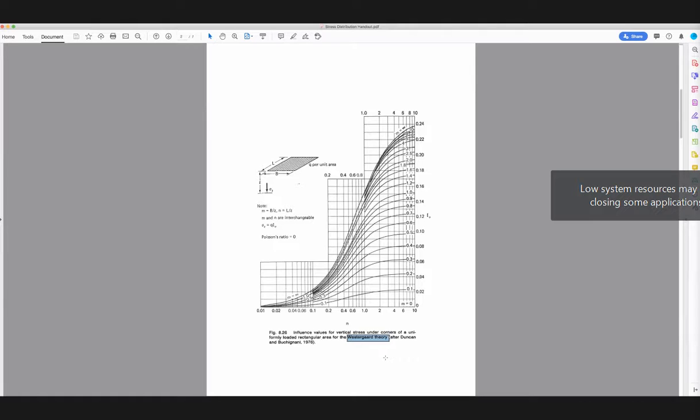But Westergaard added a layering of infinitely stiff reinforcement layers into his analytical solution on this. It has been documented to work quite well for layered soil conditions and may be appropriate for locations where you have reinforcing layers in place, such as a geosynthetic system supporting a foundation, which is most certainly a common occurrence or can be designed in that manner.